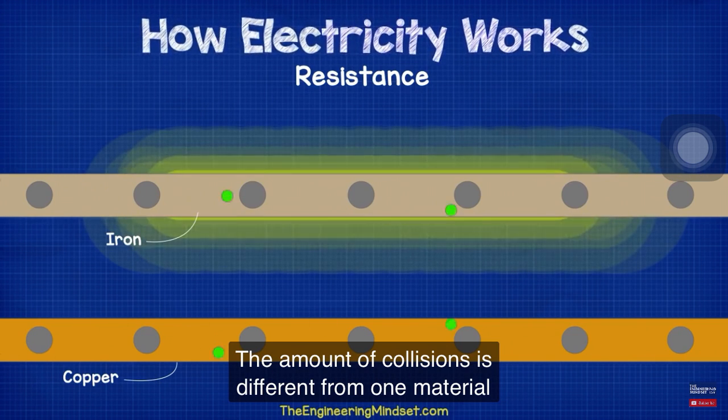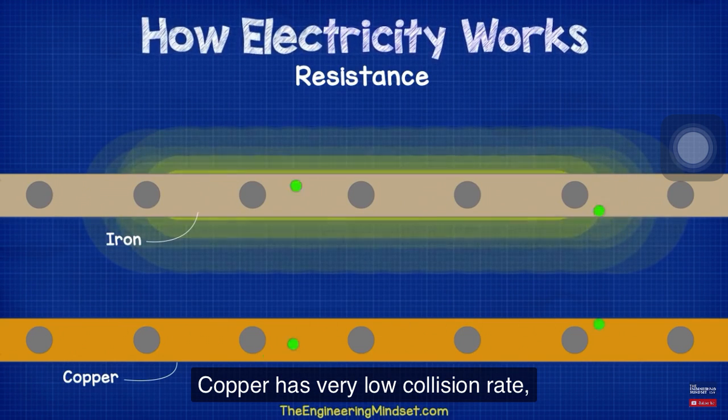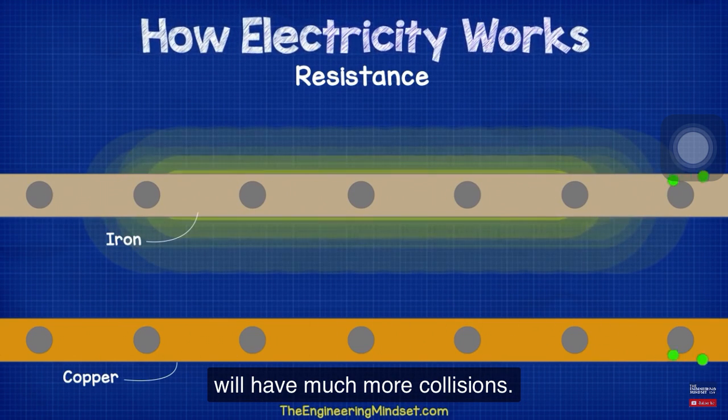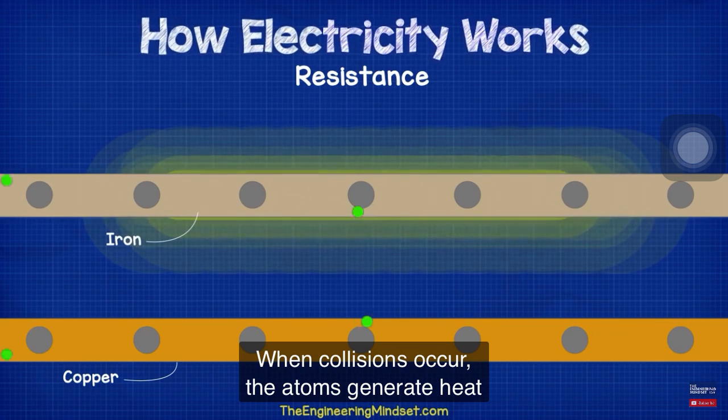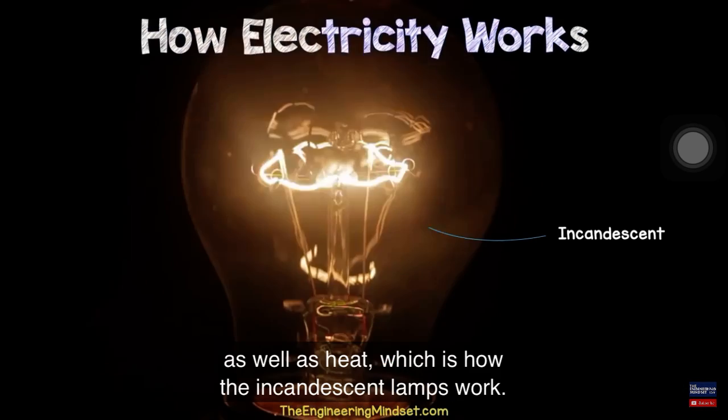Resistance occurs when electrons collide with atoms. The amount of collisions is different from one material to another. Copper has a very low collision rate, but other materials such as iron will have many more collisions. When collisions occur, the atoms generate heat, and at a certain temperature the material will then start to produce light as well as heat, which is how incandescent lamps work.